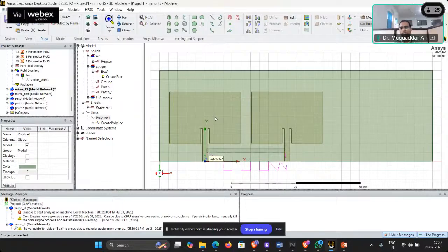The second limitation of this is the transmission line. So we want an exact 180-degree phase shift, right? So for a fixed transmission line length, the 180-degree phase shift will be only for a particular frequency point. Otherwise, it will be different. At some point, it will be 170. At some point, it will be 190-degree. So this kind of method gives isolation improvement at a particular frequency or in a very narrow band. Okay.